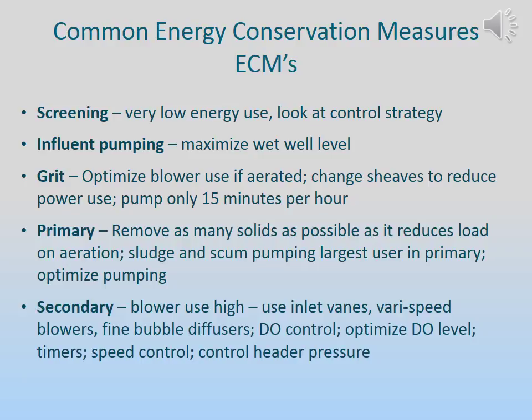Screening. This is typically a low energy user because it usually uses small horsepower motors. But looking at the process side of the operation, this is an option. Look at the control strategy. The screen start and stop cycle. Can it be adjusted to limit the runtime? There are treatment plants that run the screens 24 hours a day. Maybe they should have time control or differential controls.